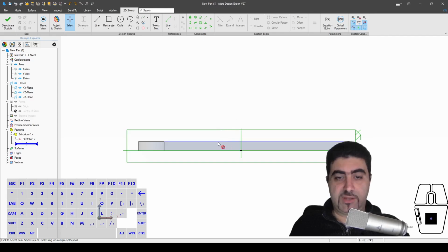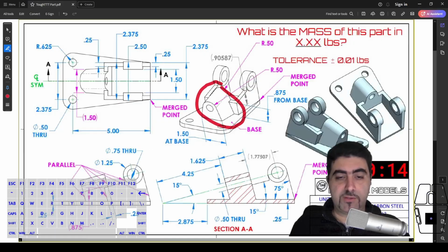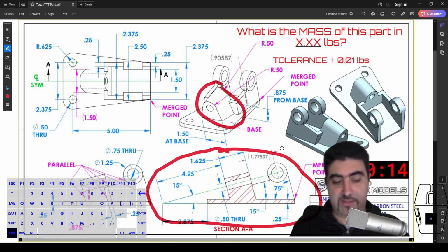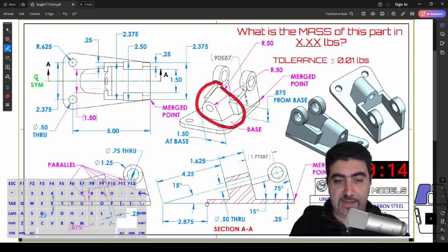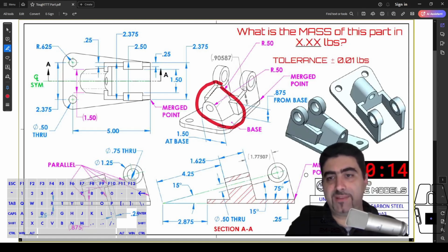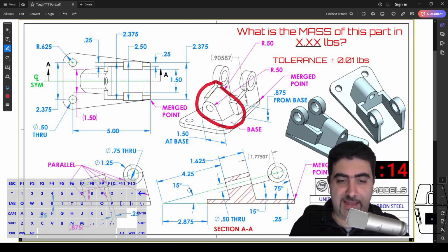So this is the top side, okay? So I will now reference this view, right? This section view. So I have this line that's 2.875 inches from the edge of the piece right here. Okay. And then from this point starts this axis. Now there are many, many things that are going on here. First of all, this axis needs to be at 15 degrees to the floor.